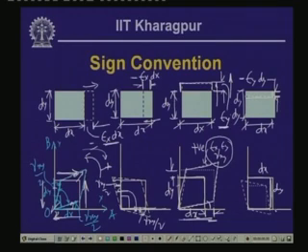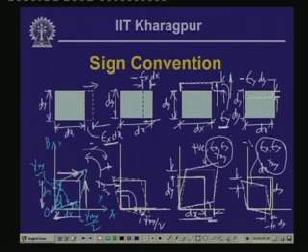now it undergoes strain, but in the opposite direction, or gets compressed. So, this is the negative epsilon x dx, and again here in this particular direction this is the deformation, it gets compressed, which is epsilon y dy, and it has a negative shearing strain, and because of that the angle increases, and when we combine all three strains it takes the shape in this particular form. So, this particular configuration corresponds to epsilon x, epsilon y, gamma xy, where all three quantities are negative. So, this is the sign convention which we follow,